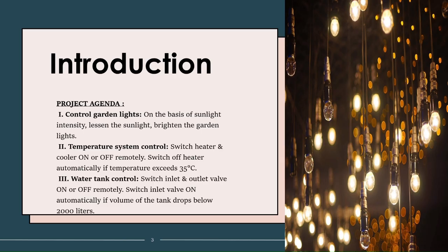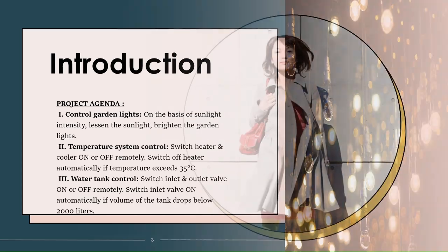We come to the water tank control. The water tank will automatically control the inlet and outlet valves. When the water level goes below 2000 liters, it turns on the inlet valve to fill the tank, and when it's full, it turns off automatically.